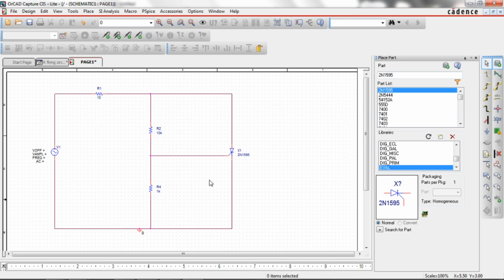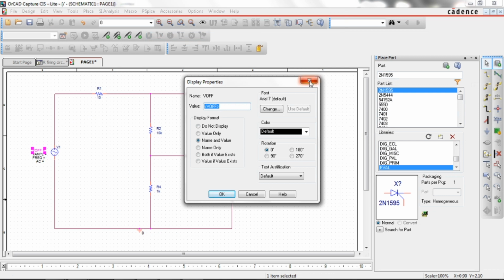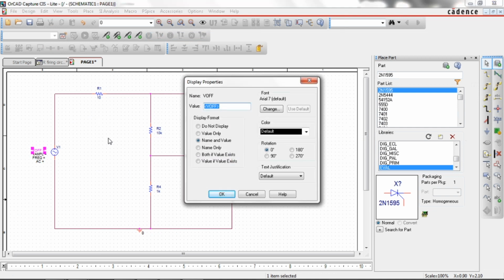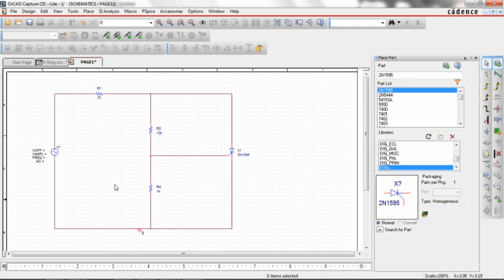See, what we did here is, this is my power circuit part. I have connected a resistance. Why exactly? I will tell you. What is a power source? See, this is our VOFF, that is an offset voltage. Here we are not giving any offset. Offset you make it 0, or you just write 0 only. Or else if you keep it blank also, nothing happens.